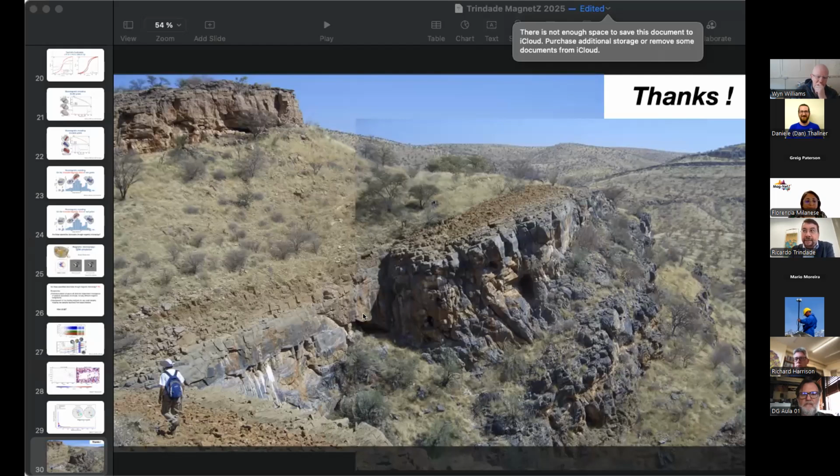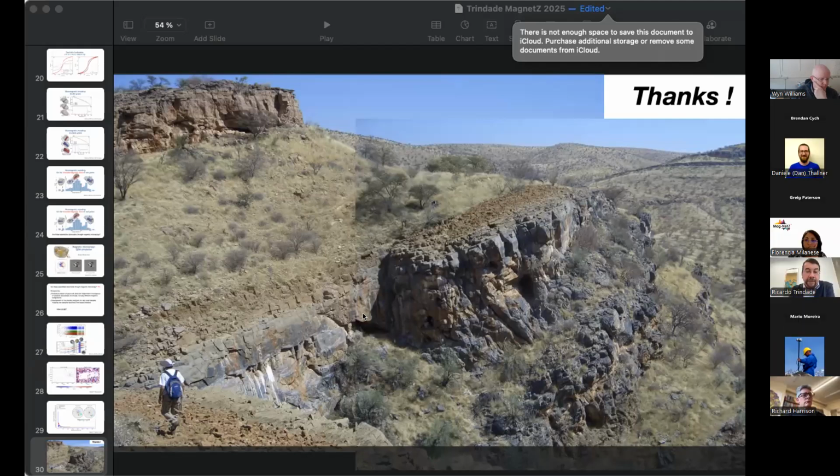The other technique that can reveal this is FIB-SEM, slice and view. There's a technique using the focused ion beam that can also, through the erosion of several surfaces into a sample, provide a three-dimensional reconstruction of the grains. So that's another possibility as well. That has been used by Harrison's group in some papers.